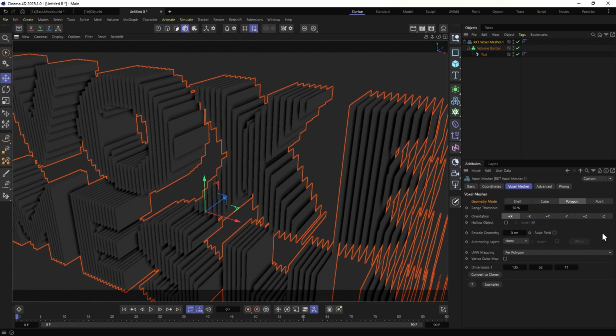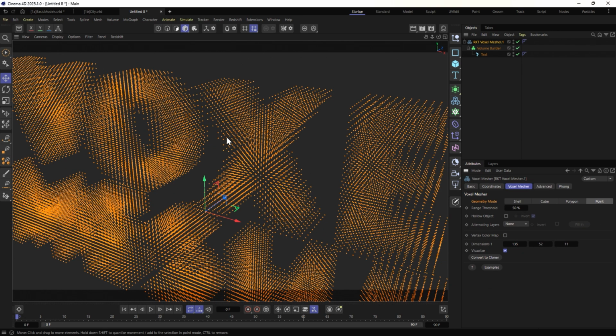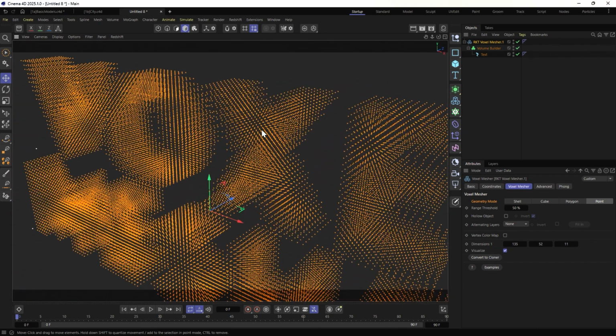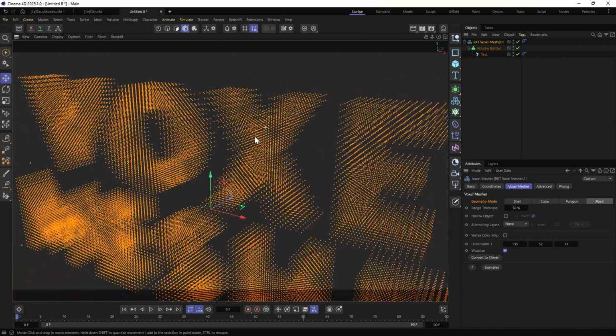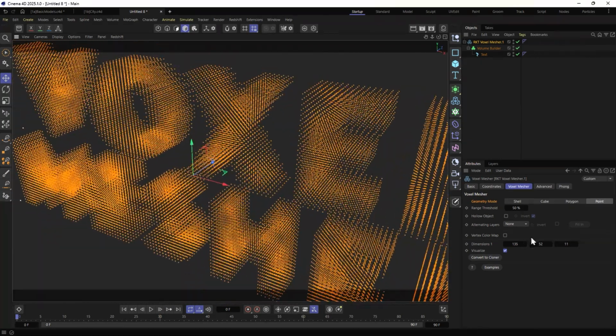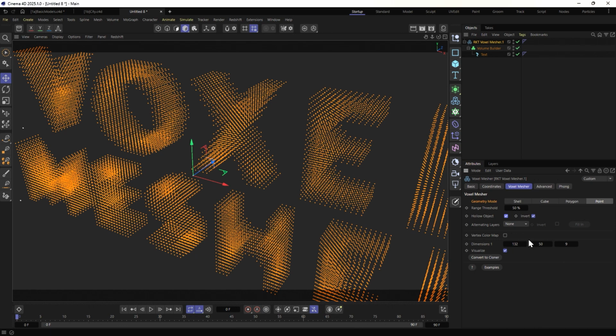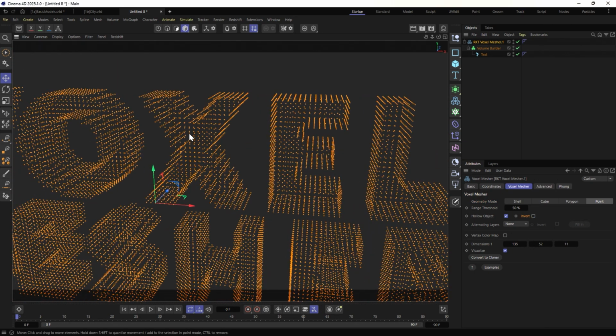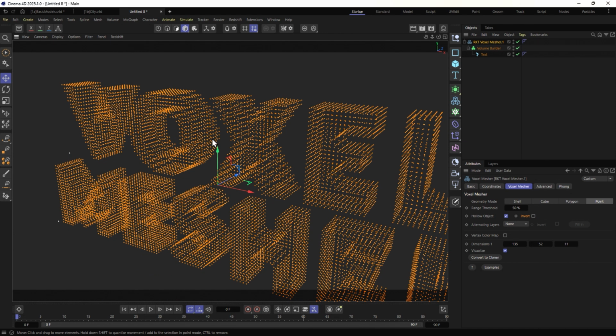And our last mode is going to be our point mode. And what this is going to do is just create a point cloud for you. And this is primarily for the purposes of, I suppose you could render directly on those dots, but mainly that you can clone onto them. So we have exactly the points only as we want to return them. So I could say, give me a hollow object and don't invert. And now you see we get this outer shell of points perfectly for a voxel setup.